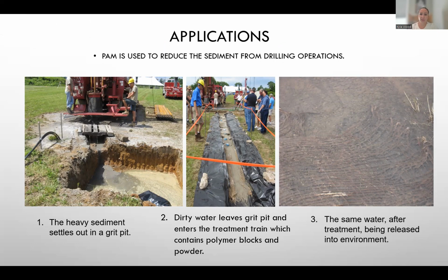This was just a demonstration scale, but we also have applications for drilling and pipeline work. So we have a lot of turbid water that's coming out of those holes. And so what we did here, for this demonstration in Pennsylvania, is we had a sediment or grit pit to settle out the high solids. And this leads to an important point, that the flock logs specifically are designed to treat turbid water. They're not going to treat mud.